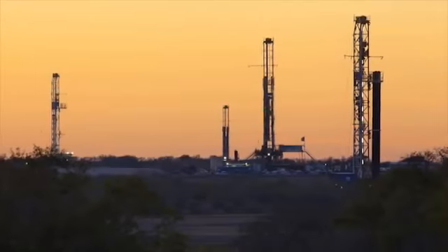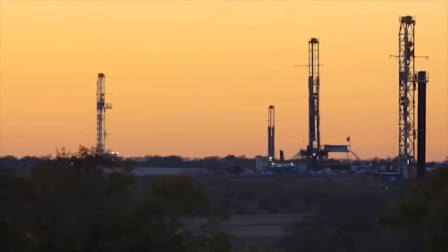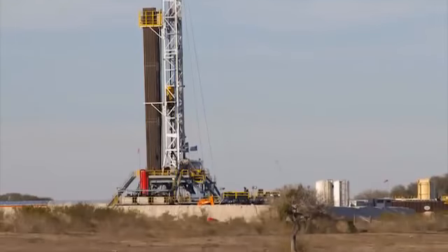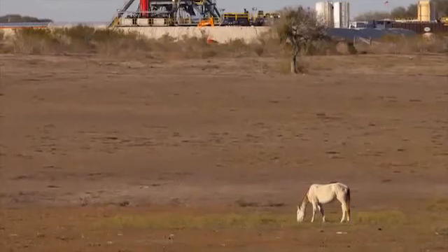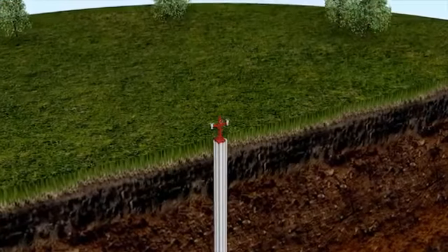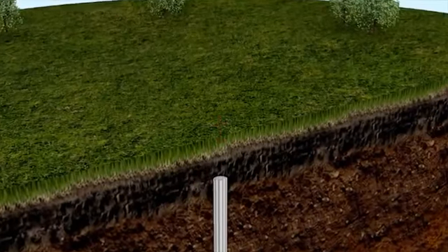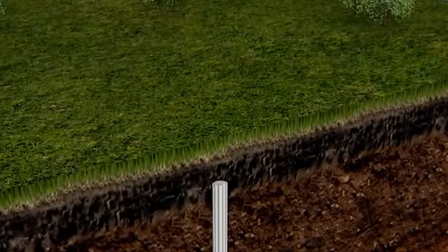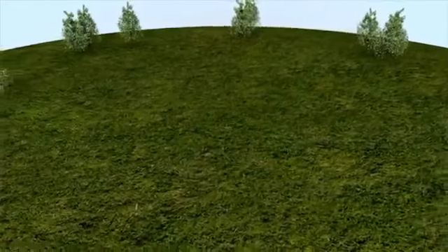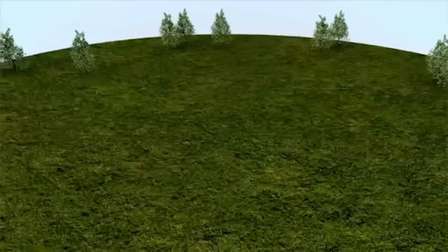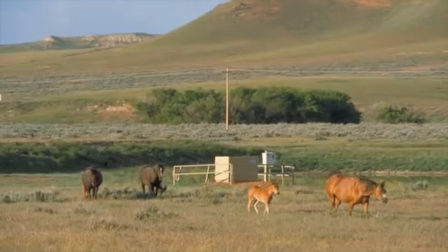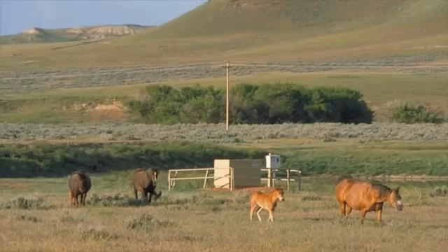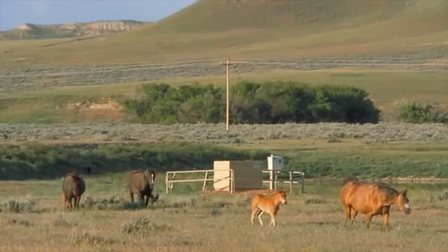When all of the oil or natural gas that can be recovered economically from a reservoir has been produced, work begins to return the land to the way it was before the drilling operations commenced. Wells will be filled with cement and pipes cut off 3 to 6 feet below ground level. All surface equipment will be removed, and all pads will be filled in with dirt or replanted. The land can then be used again by the landowner for other activities, and there will be virtually no visual signs that a well was once there.